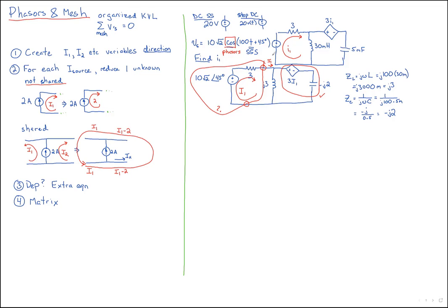And since that's the same as the I1 in here, even though after we transform it none of the internal voltages and currents we can consider will be the same as in this, everything outside has to stay the same if our transform means anything. So therefore we could. And with two source transforms, we'd magically change this into something where everything is in parallel, and we could solve it with a current divider. So that's one way that you could do it.